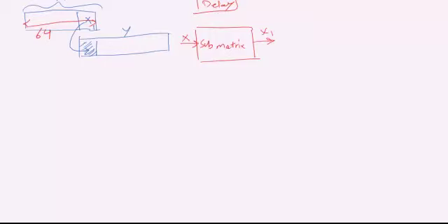One clue I can give you is that you have to define it from the last. If you double click on the properties of Submatrix, you can say copy from the beginning or copy from the last. Of course you need to copy from the last part. I'll leave it to you to configure the Submatrix block.